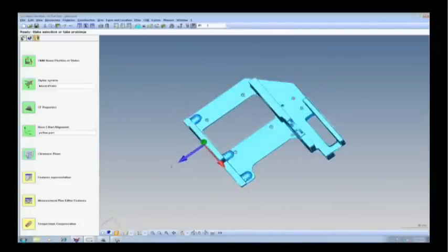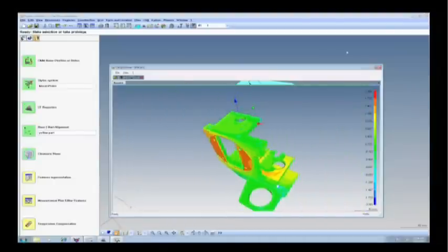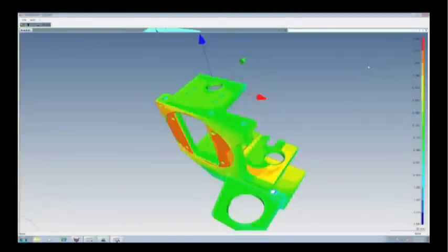before we even venture into sitting down and building a measurement plan, I can very quickly overlay this on top of my CAD file and do a first article type inspection. This is the same measurement plan that was created on the Faro arm, measured on a CNC CMM, and now we've used that same measurement plan to control the Metrotome, to take the same data.